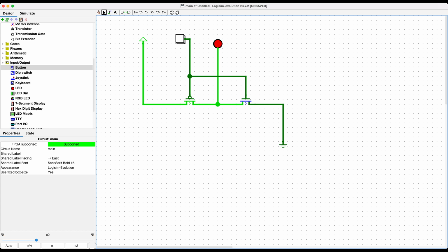That's what NMOS and PMOS basically are. NMOS is default open, meaning you have to exert effort, you have to deliberately close it, like pressing the spring-loaded button. PMOS is the one that's spring-loaded closed, and you'd have to exert effort to turn it off. Does that make sense?